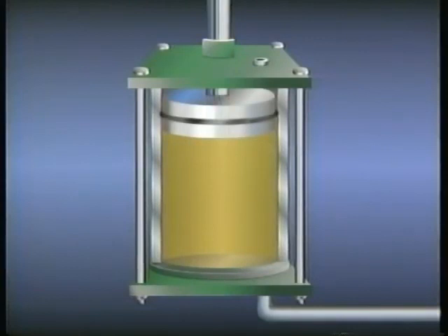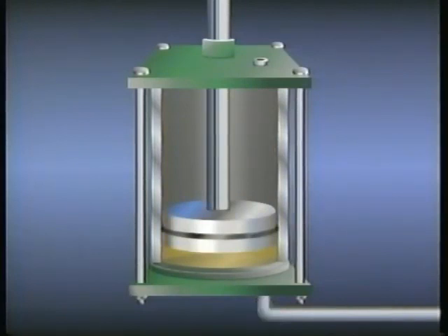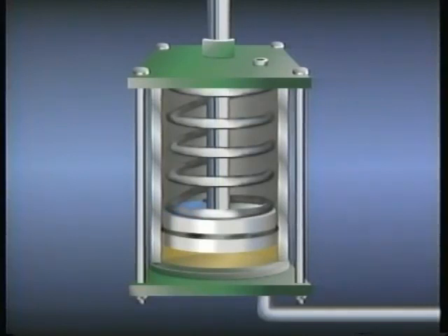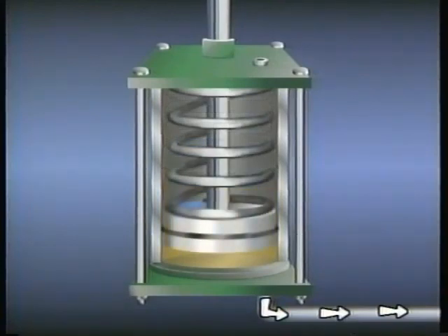When the flow of fluid stops, the piston and piston rod stop and are held in their new position by the fluid trapped under the piston. When fluid is allowed to flow back out of the actuator, the weight of the load causes the piston to move downward. In some single-acting actuators, the piston may be assisted in returning to its original position by using a spring in the cylinder. When fluid flows into the cylinder, the piston rises and compresses the spring. And when the fluid is allowed to flow out of the cylinder, the spring expands and helps force the piston back down.